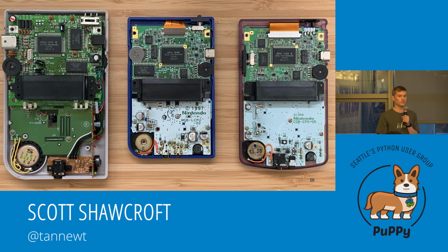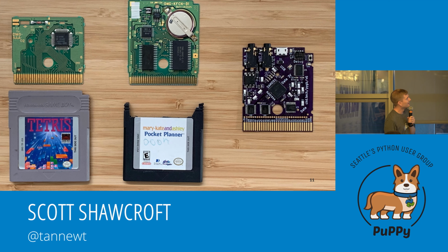That's how code is stored, right? There isn't any actual code on this piece of the Game Boy, it's all on your cartridge. What does a cartridge look like? Here's a couple. Tetris is kind of the most basic, where it's literally just a piece of ROM. It's memory that you can't change at all. The way it works is, in the cartridge pins, you get an address that says, read me this piece of data, and then on 8 lines out, you get the data back.